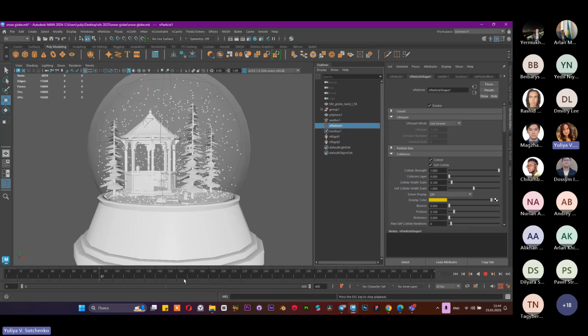If we have a really long animation, our particles become more and more numerous, so we can change their lifespan to a random range. For example, with a random range from 1 to 0, our particles are created and disappear after 1 second or 2 seconds.